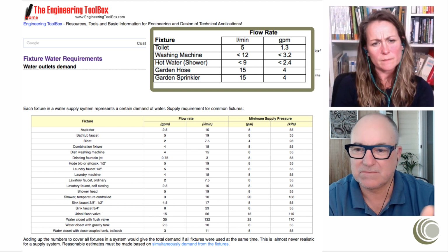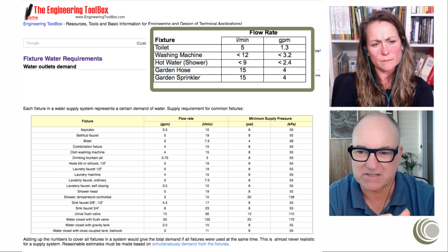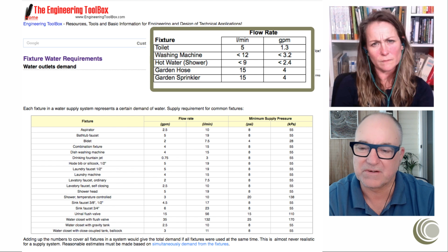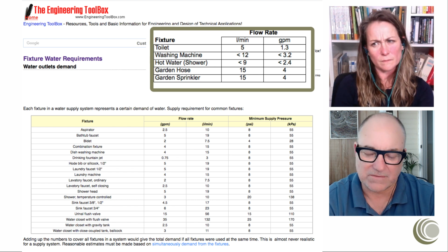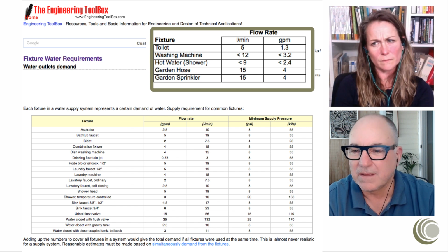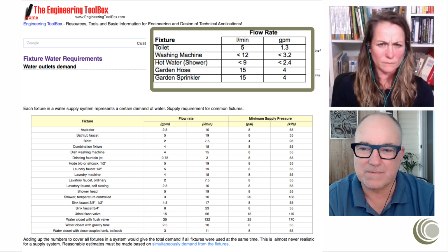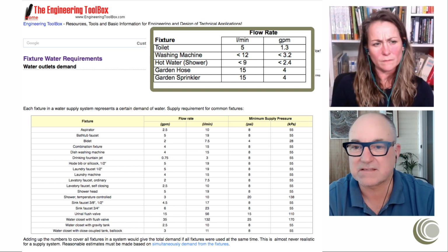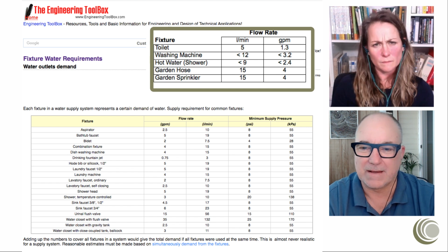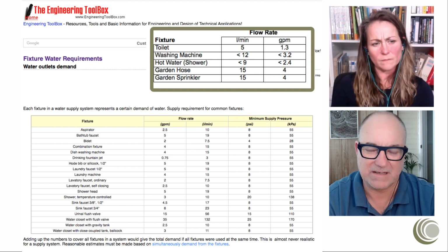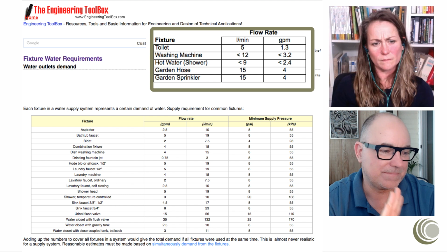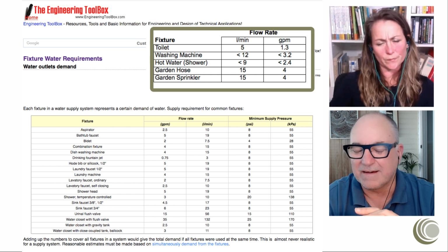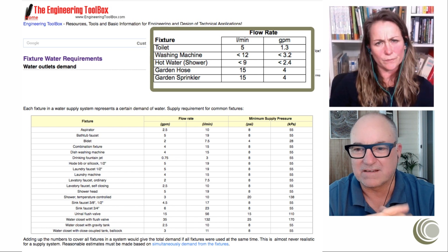Yeah, and as we talked about before, if you have a low flow, water efficient washing machine, and the saturation of those is fairly strong throughout the world now, in countries like North America, Australia and the United Kingdom, the machine itself is expecting 4 liters a minute or less of flow rate. Any higher flow rate going to that machine is being buffered by the pressure reducing valves in the machine, and a lot of people don't realise that.